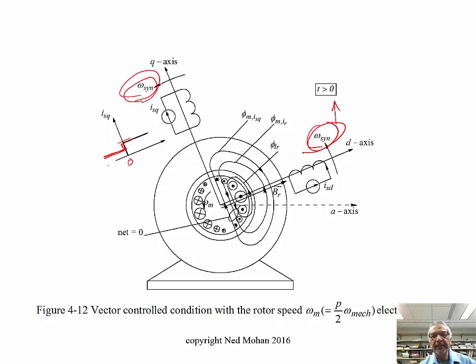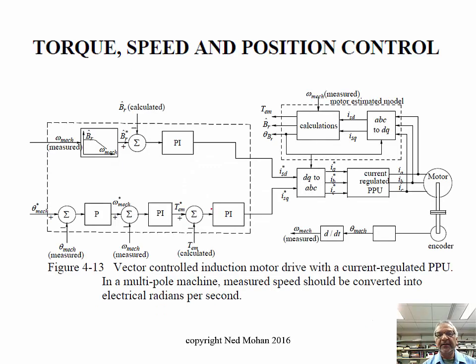So what we saw under the conditions of a blocked rotor can easily be seen when the rotor is actually turning. That's really the bottom line, because we will be making this a torque jump, if necessary, under vector control. It will be under a condition when the rotor is actually turning at a certain speed. So the main thing is that we want to keep this relative distribution the same as the rotor is turning, but these currents may be of different values to produce different electromagnetic torque.